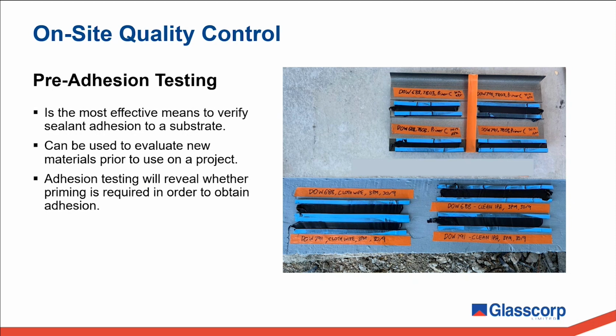Pre-adhesion testing will also reveal if any specific cleaning or priming is necessary to achieve good adhesion, or if the sealant does not adhere to the substrate at all, and a change to the specification has to be made.